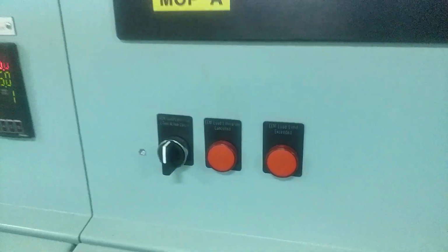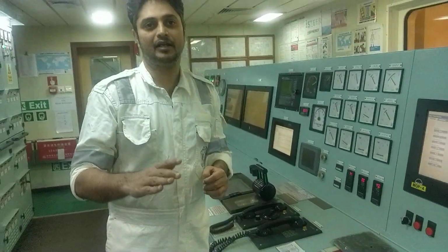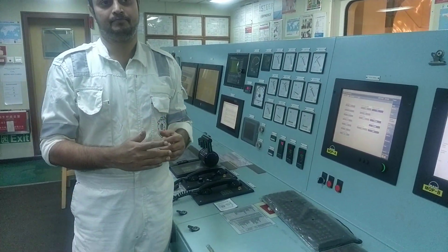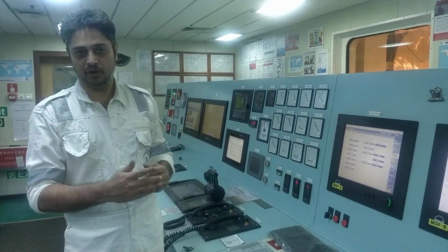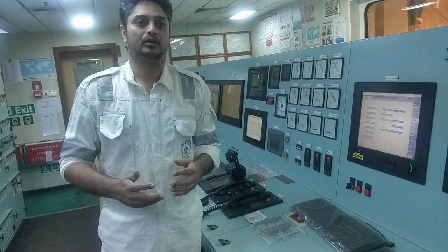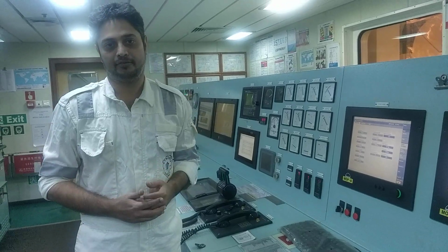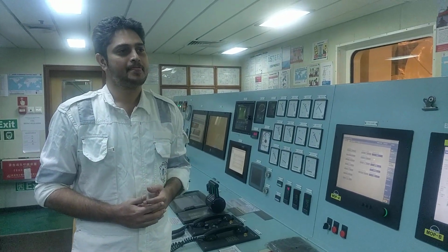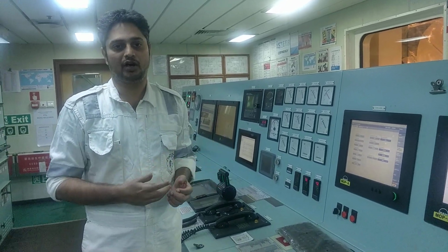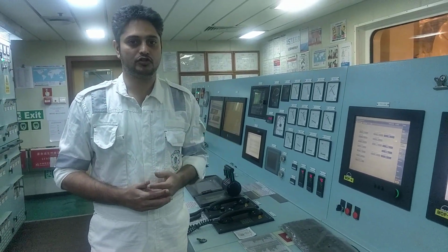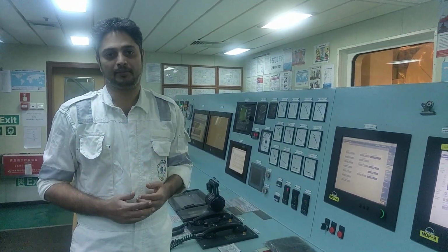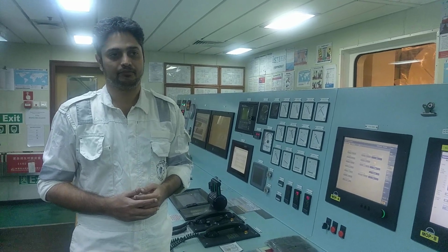Basically, what they are trying to do is limit the engine load to 80.6. Indirectly, they are limiting the fuel index so it cannot cross more than that, like locking the fuel index. Since it's an ME engine, it is done using software and cabling. There is no mechanical stopper. But in an SMC engine, you have a mechanical stopper down below at the fuel rack, the regulating shaft.